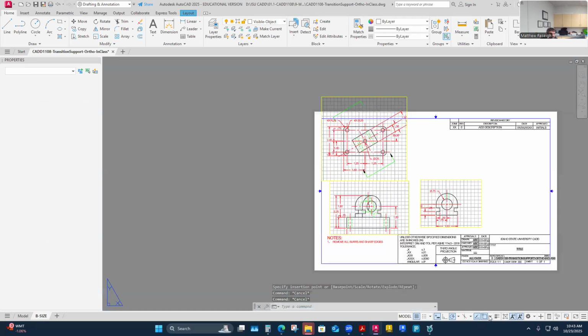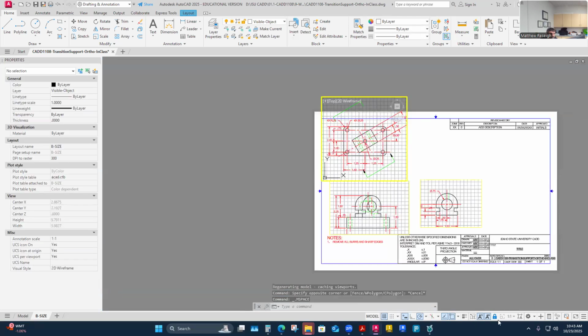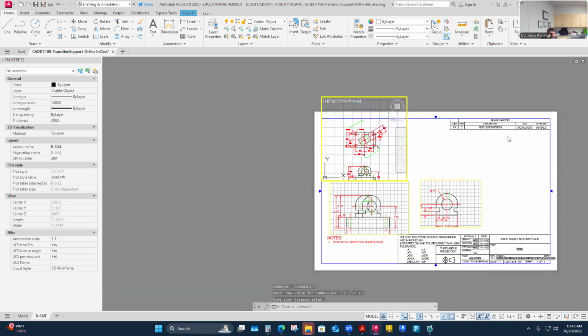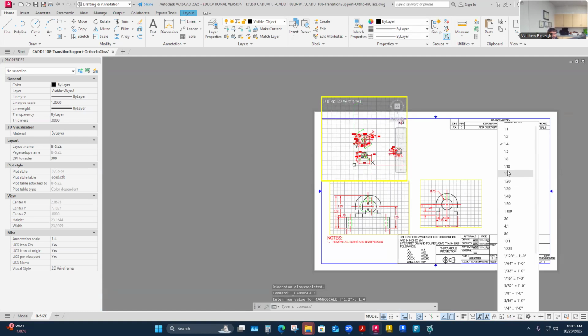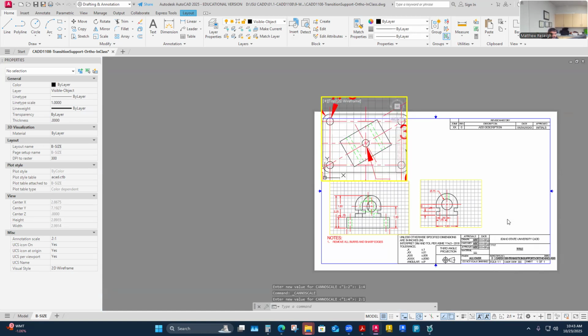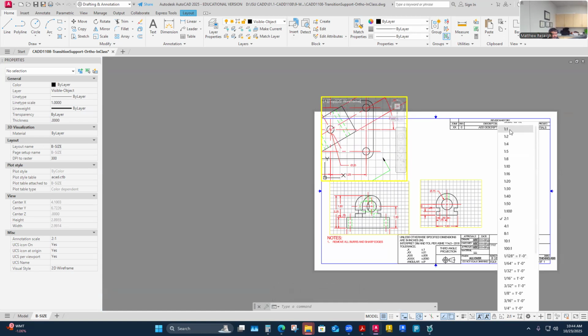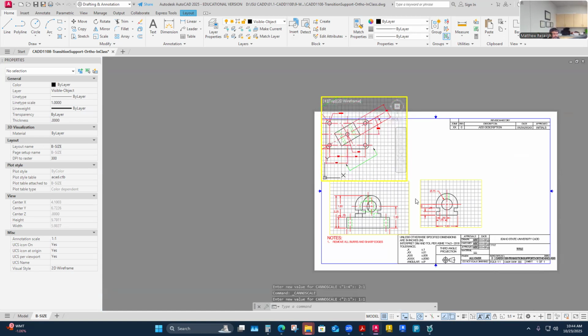And then all we're looking to achieve is, if I come in here to this viewport and I end up changing its scale, I want that arrow to flex for me. There it goes. I can see it change its size. If I double it up, it auto adjusts for me. It looks like it's double the size of that little dimension arrow there. Heck yeah, so that's working for me good. 1-to-1 is what it'll be though.